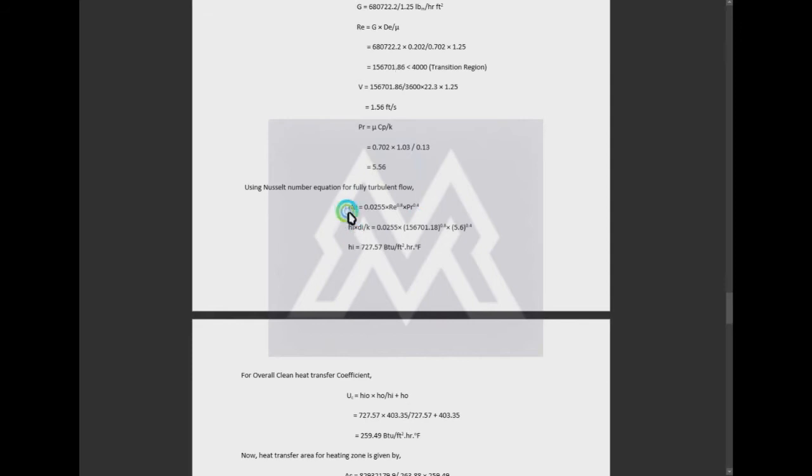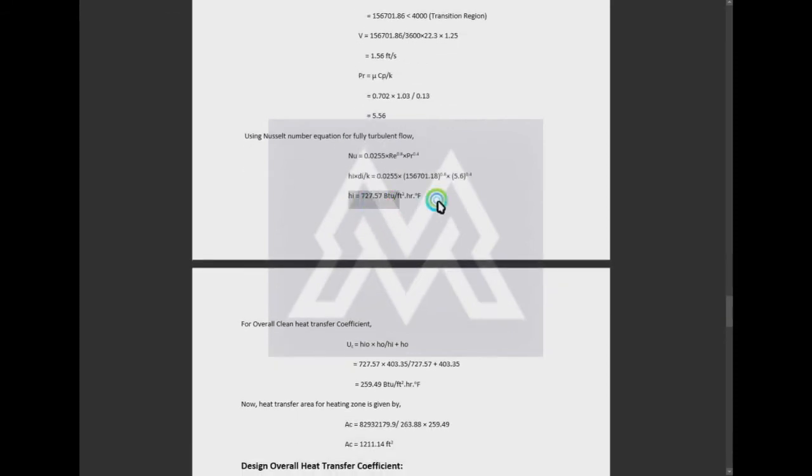So we will again use the same formula for the calculation of the heat transfer coefficient, and Hi will come out as defined before in the last video. Here we will not correct anything, because the inner shell heat transfer coefficient is what matters, and the outside will be air, outside of the heat exchanger, so we do not have to do anything with that.